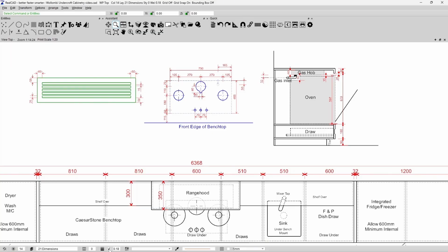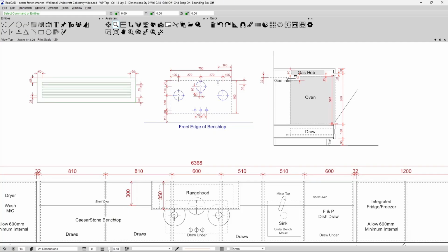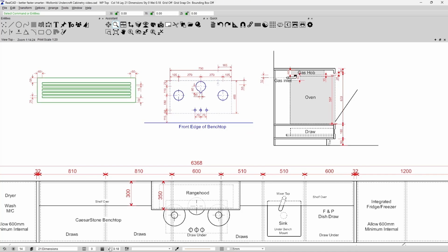Here we have the ability to switch on or off the display of line thickness. So you'll notice in this drawing we have different line thicknesses. And if I uncheck this option, all lines are now drawn at the thinnest line your screen is capable of displaying. When you tick the option, lines with a variable thickness or lines with a thickness greater than 0 will show up slightly thicker.